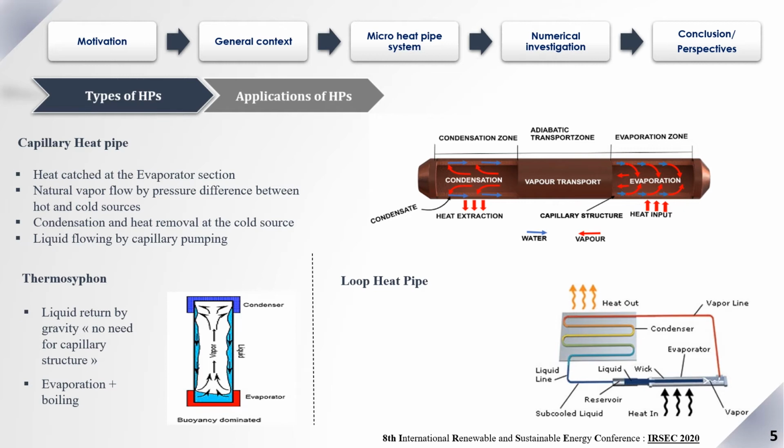Loop heat pipe possesses all the main advantages of conventional heat pipes, but owing to the original design and special properties of the capillary structure, it is capable of transferring heat efficiently for distances up to several meters at any orientation in the gravity field, which makes it a desirable device for thermal cooling in aerospace application.